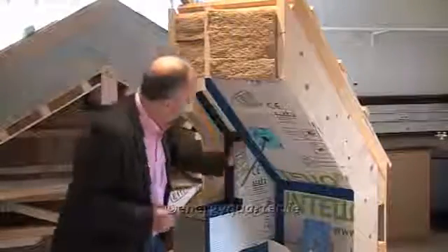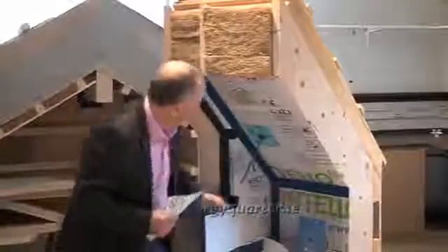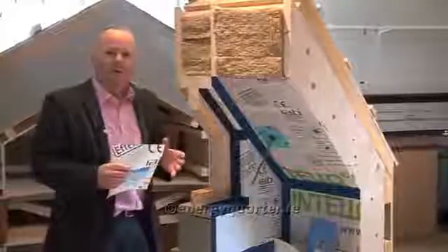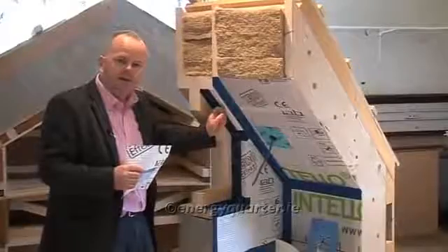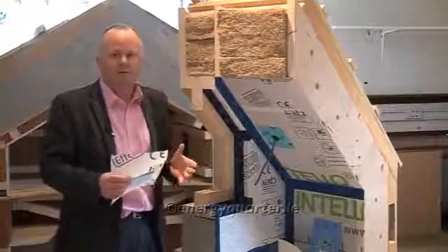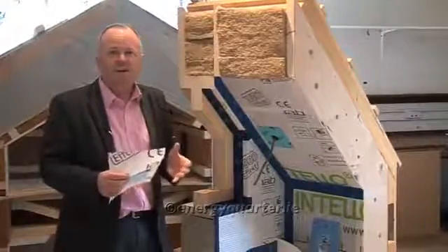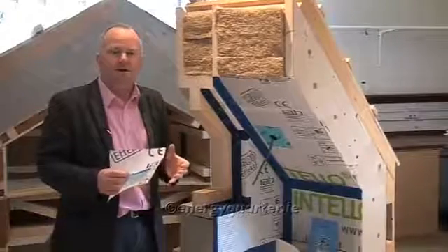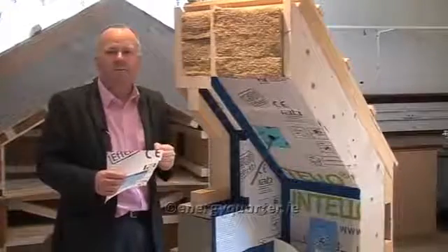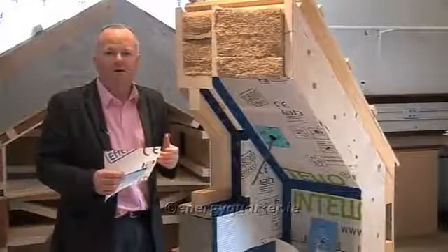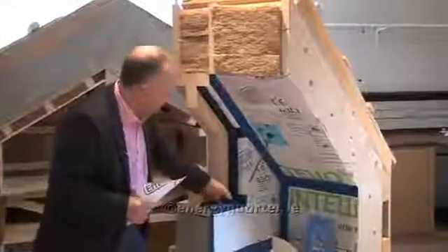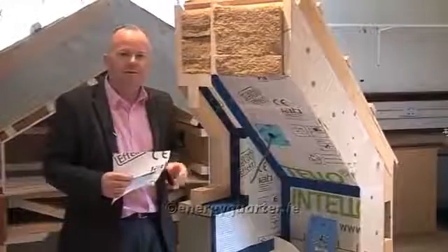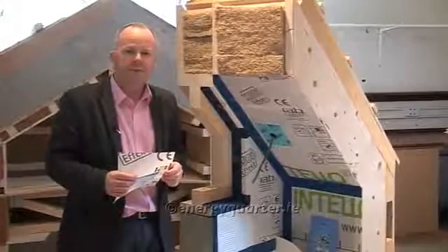So we use this special proprietary tape here, and then we also want to make sure we get a very good connection between the window frame and the main structure. And again, you can't trust plaster to achieve that level of airtightness, because over time the plaster will shrink and pull away from the timber frame and you'll have cold air infiltration. So again, we use a special proprietary taping system to achieve this very high level of airtightness.